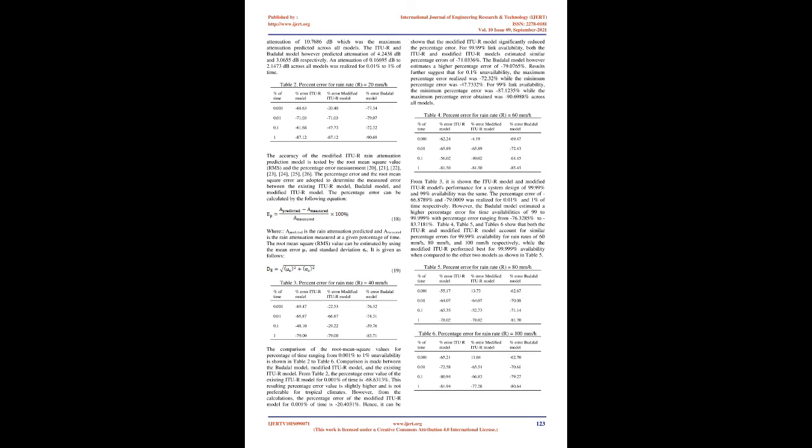It was also observed from Figure 2d that the attenuation due to rainfall recorded a maximum value of 21.9838 dB for 99.999% availability and a minimum value of 6.7175 dB at 99.999% availability based on the modified ITU-R and Budalal models respectively. The ITU-R model, however, predicted attenuation of 8.6636 dB for a system design of 5.26 minutes of outage in a year.